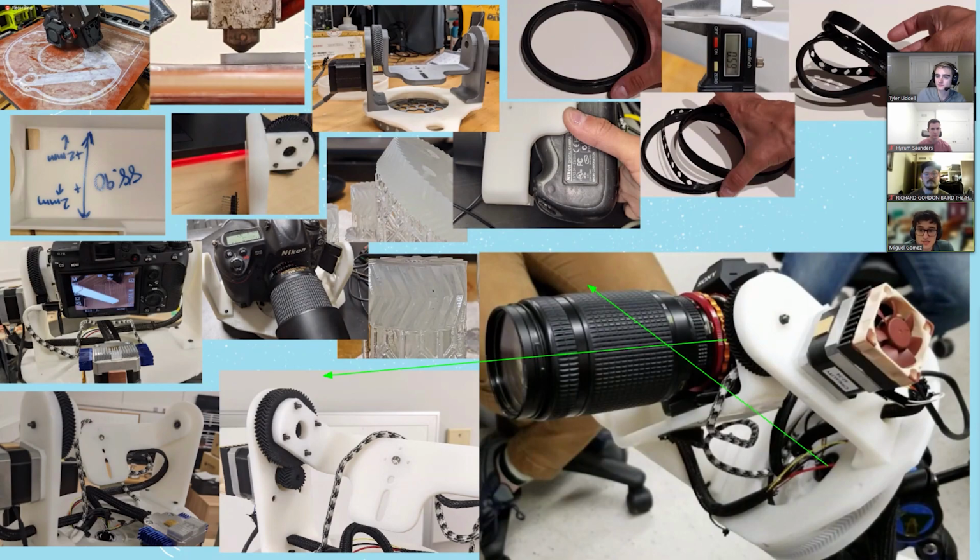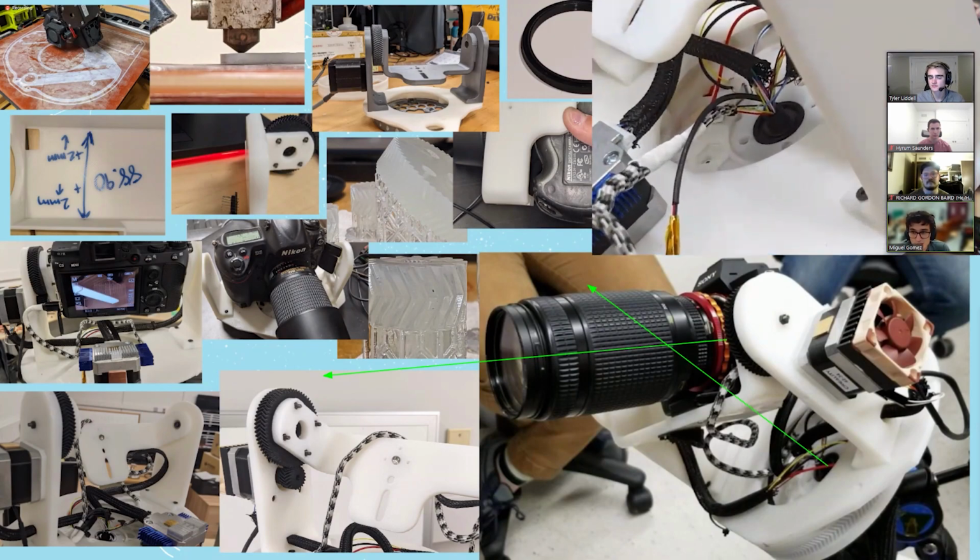And on this next little image here, you can see that all of this, in order for it to not get tangled up and messed up, it needed to go through a slip ring, which actually caused us some signal integrity issues with USB. But it ended up not being a problem since we solved that, but it's still something to consider.